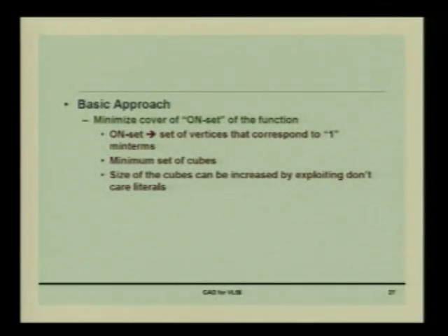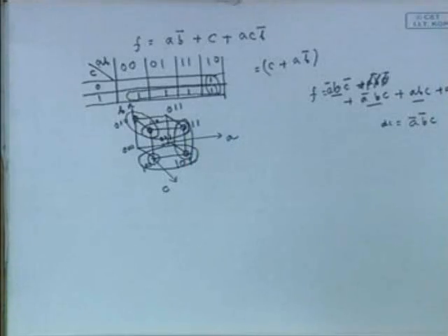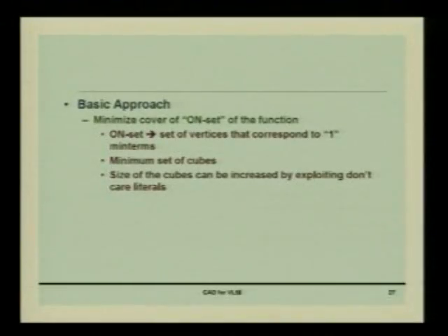Cube means you are encircling two or more, 2 to the power n, on terms. These are called cubes, these are not cube shaped. You can circle that.